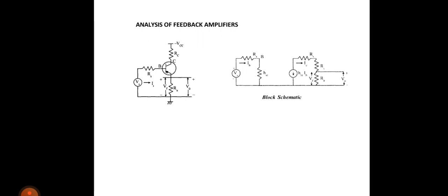So only RC and RE will be there at the output side. Then connect RC and RE at the output side. Now join the input and output circuits as shown in the figure at the right side. Okay, then replace the transistor with the simplified hybrid model or approximate model. Then we will find the gain.